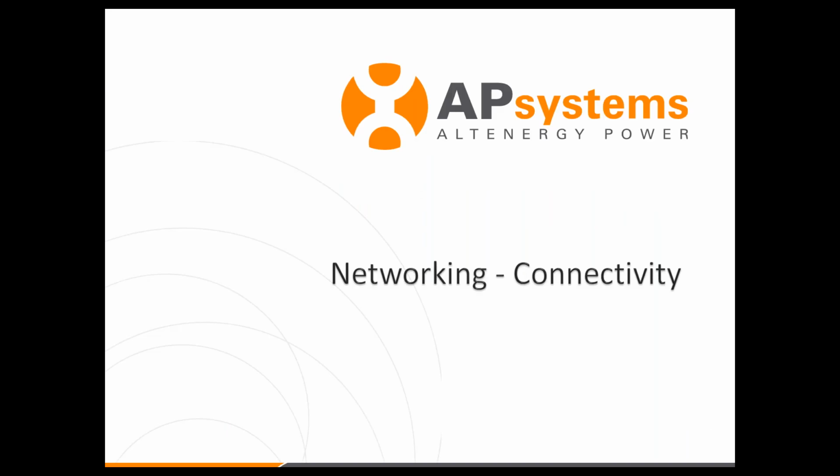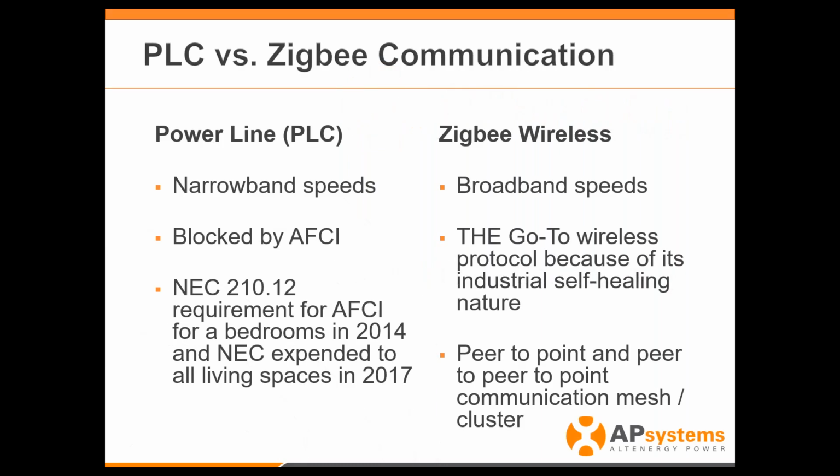Okay, let's talk about networking and connectivity. This is one of the places that really slows down solar installers, and this is very valuable. Like we talked about before, APsystems and other solar inverters utilize PLC technology. PLC has been around for a long time, and it's a fantastic technology. But with NEC 2014 came the advent of putting arc fault breakers in all bedrooms, and in 2017, making it even worse by putting arc fault breakers in all living spaces.